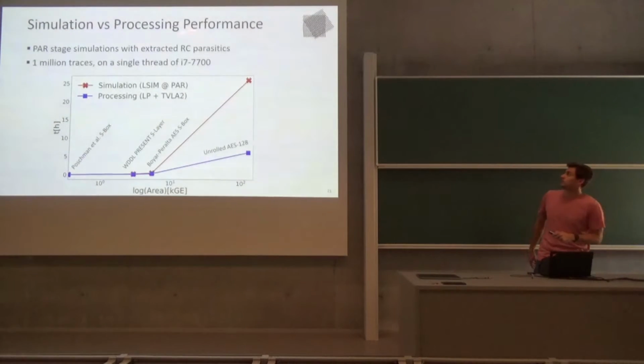So first of all, there was a big question about how this scales. For instance, if you take SPICE, it's the best analog model, but you have an exponential increase in processing times with the increase of the gate sizes. If you're using these sorts of logic simulators and also the more sophisticated power simulators that are on gate level as well, they scale pretty much the same.